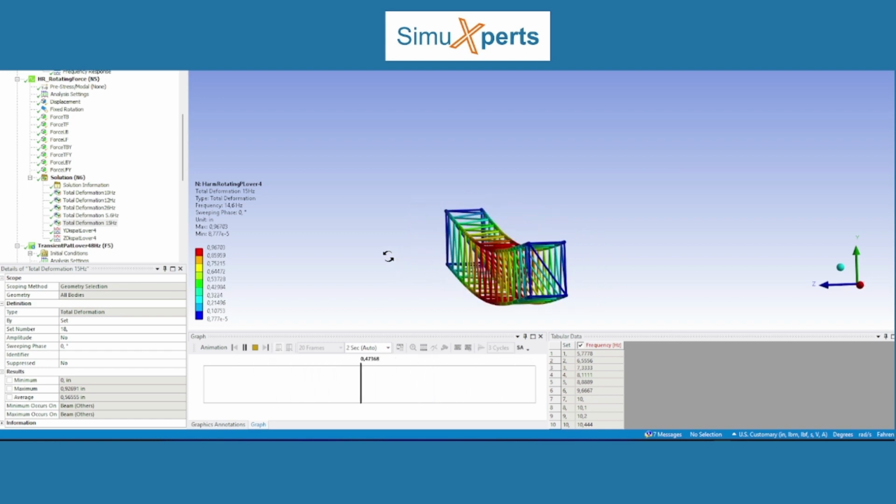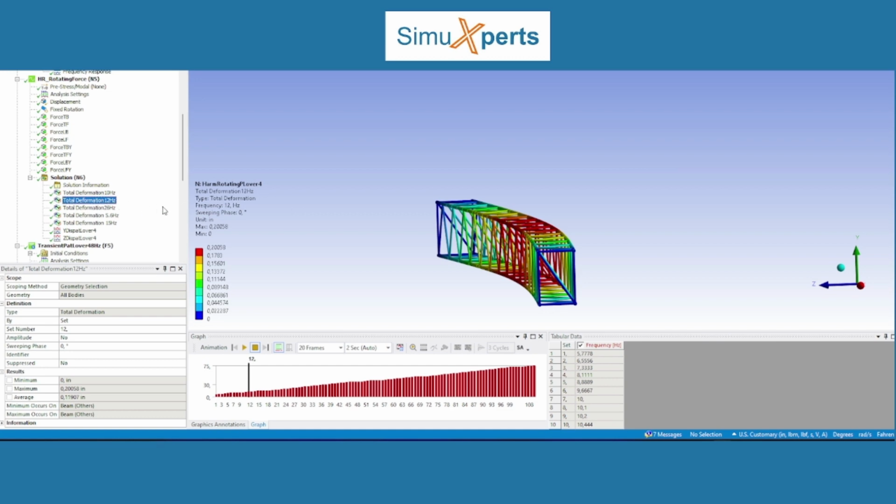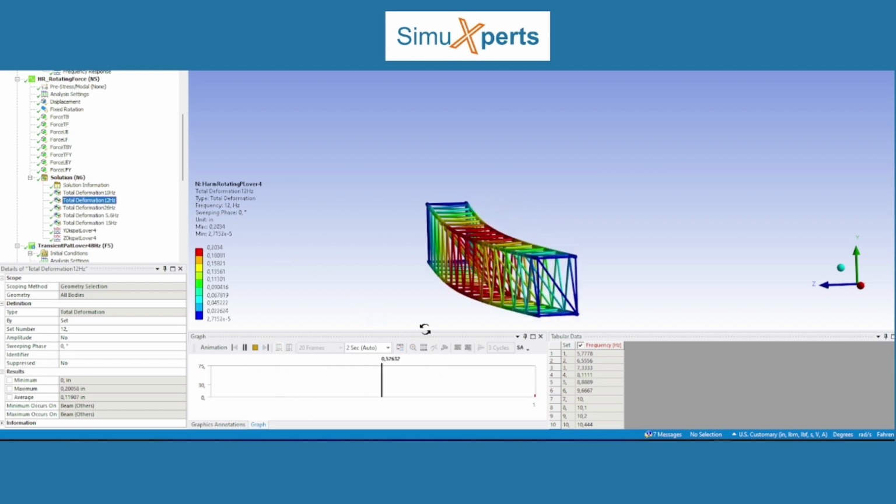Now what's interesting: when are we going to see the structure rotate? Because remember that the forces are rotating forces. Well, the best place where you're going to see this is when you pick a frequency that's between the first bending mode around the weak axis and the first bending mode around the strong axis. And in this case, we're looking at the results when the forces are applied at 12 Hertz.